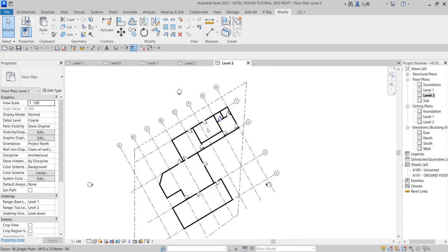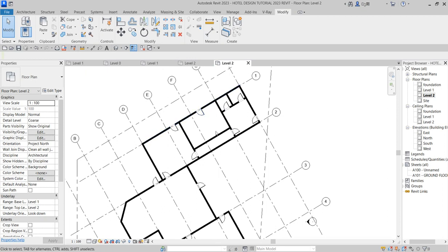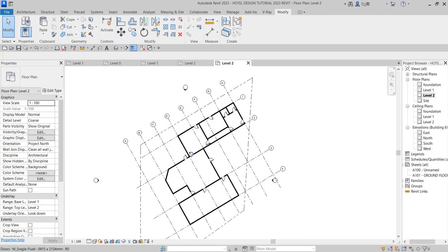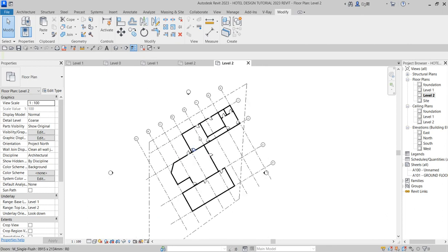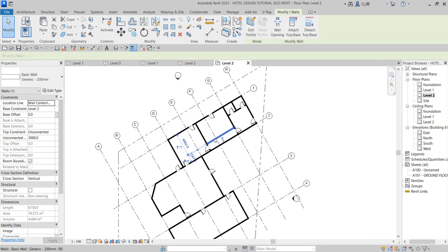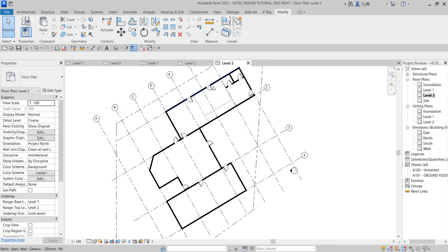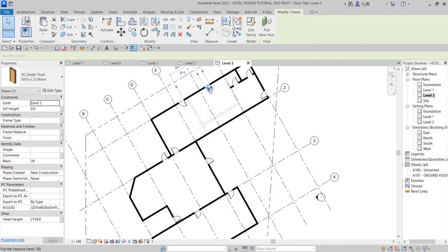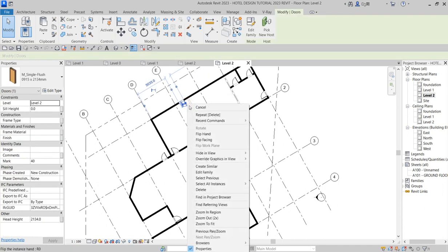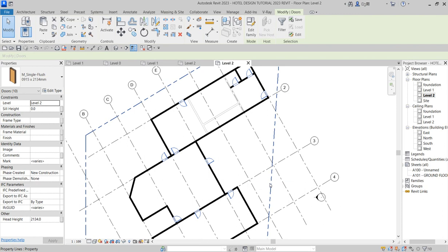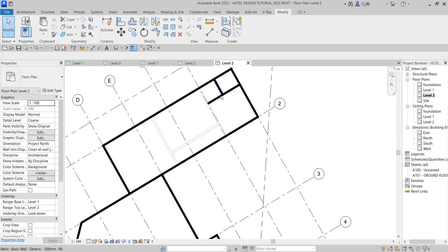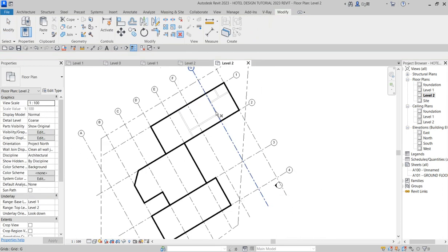The next thing to do is cantilever this space and create our rooms one after the other, depending on how many rooms we can actually have in this space. So delete all the internal partitions. Select this, say select all, and delete them, but we're doing that one after the other. Select all, then click on delete. I don't want them for now. I just want to concentrate on demarcating my rooms and giving them a befitting layout.